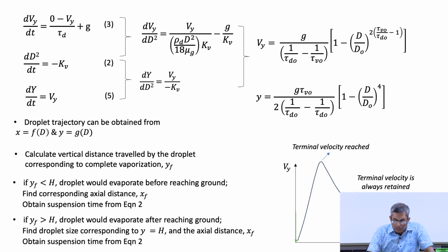But here you have to make sure that you calculate Reynolds number at every time step, because the slip velocity is changing, the particle size is also changing. Similarly, the particle relaxation time also changes. So you need to update this at every time step. But once you calculate this, just plug in all these here, okay, and go on evaluating the velocity.